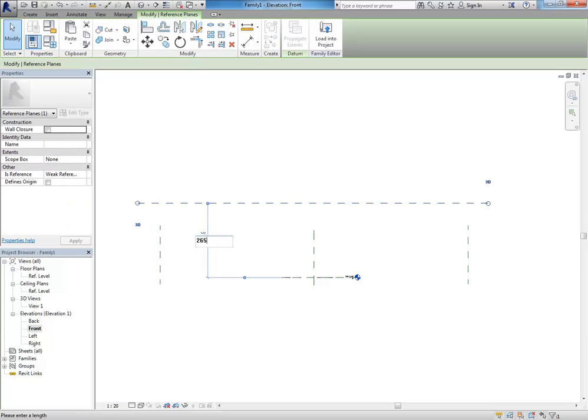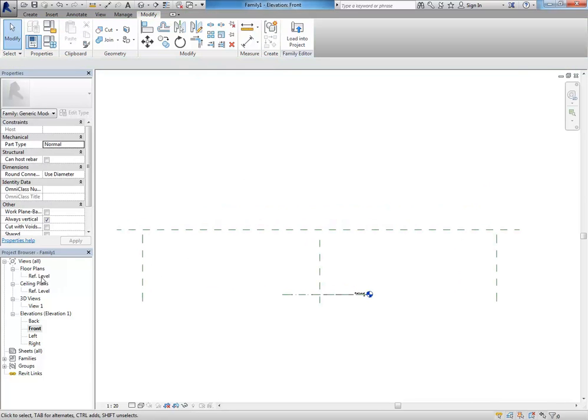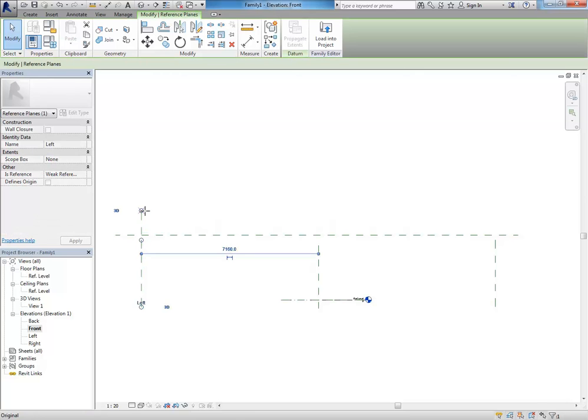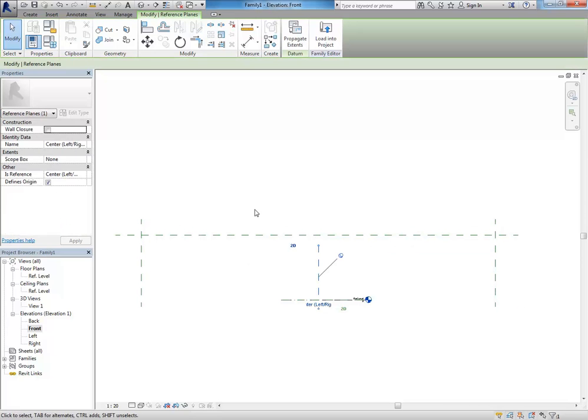So probably good to see that, because it's a common mistake people make, forgetting to change to the appropriate view when you're making things that need to be projected or from the side. Okay, so I'm just stretching these planes up so they are a little bit higher, and it will sometimes let you stretch these initial planes as well, so try that.